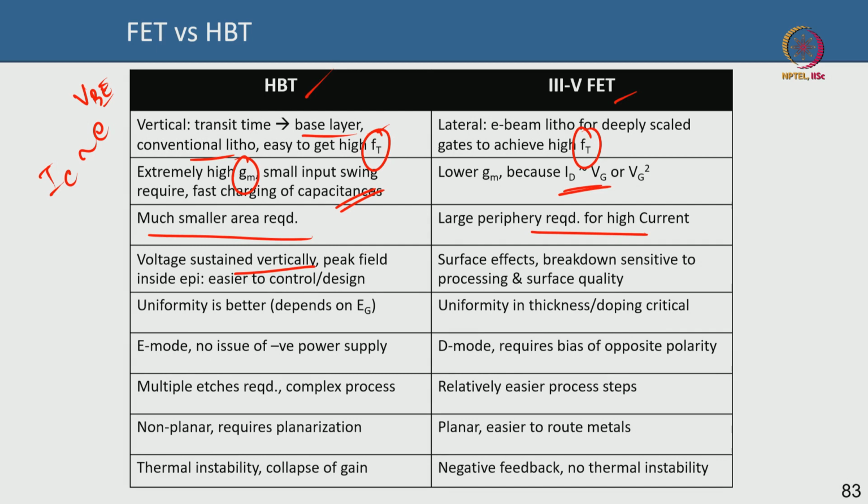dangling bonds, moisture, etc. effect. But in a transistor like a lateral field effect transistor, in your gate drain region, all kinds of moisture, passivation, surface dangling bond defects, etc. can really impact your cutoff frequencies, and your breakdown is very sensitive to the surface, okay.